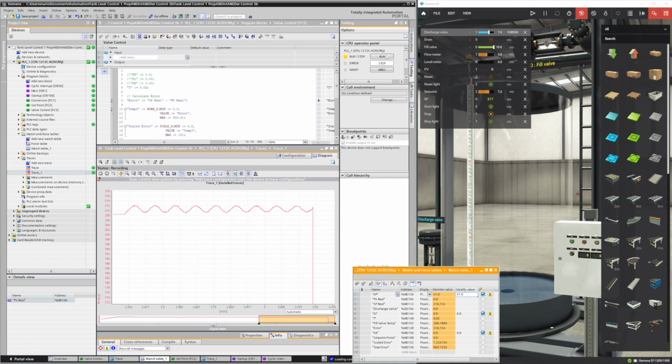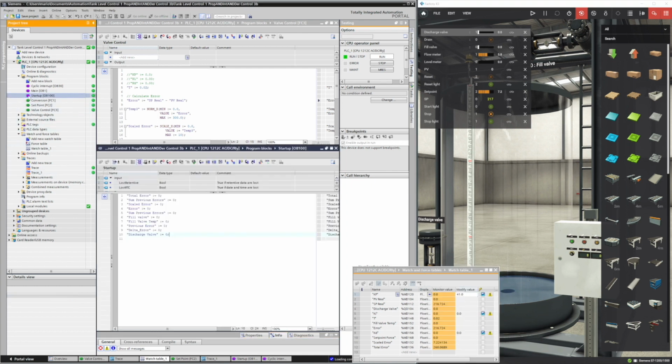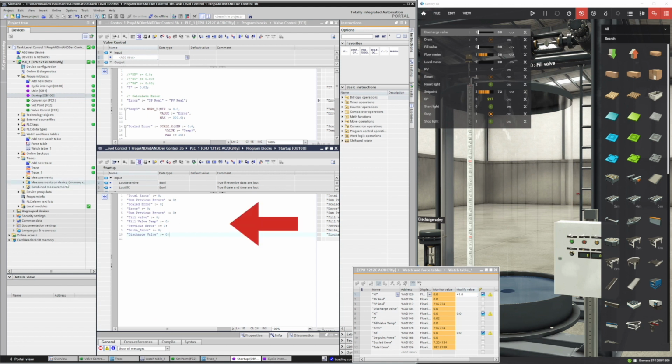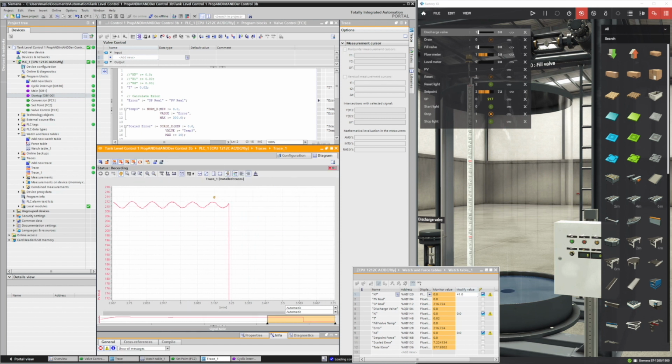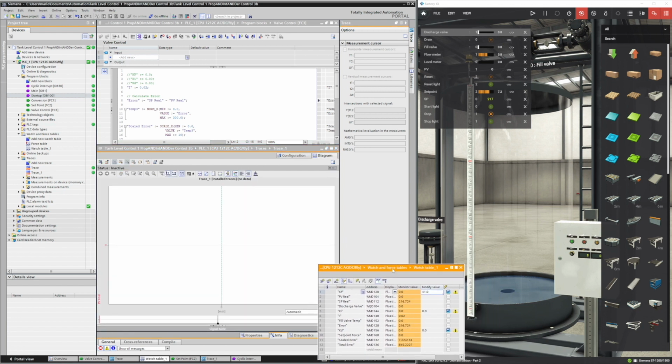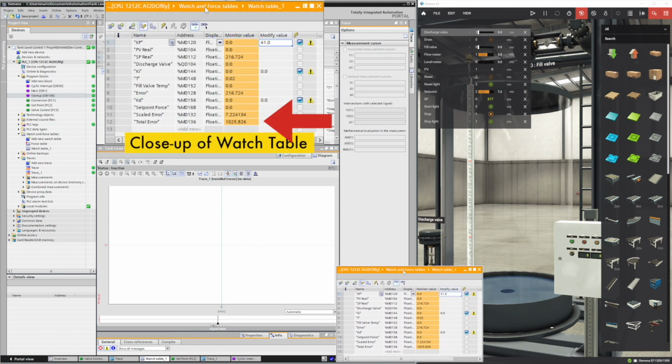Now let's start the PLC again so that all the variables are reinitialized to 0 when we put the PLC into run mode again via the startup OB100, as we can see here. Let's also start a new trace, so delete the old one and prepare for a new one. As you can see, we are still getting readings of total error on every scan, as this is the accumulation of the scaled error used for the integral part of the algorithm, and we will see why that is happening when we get into programming.